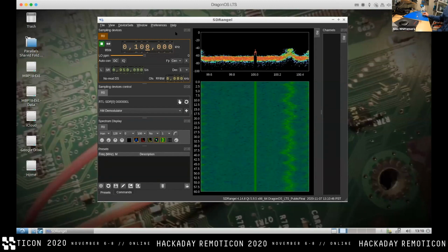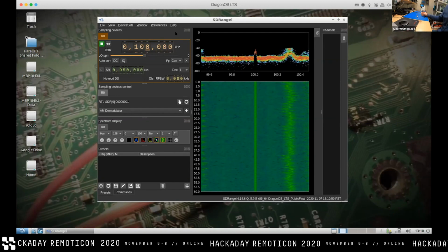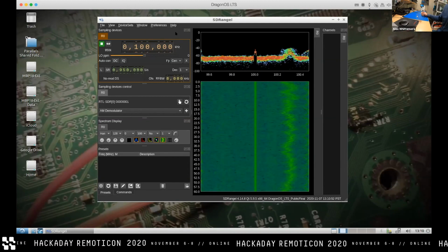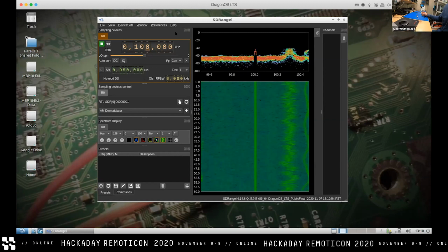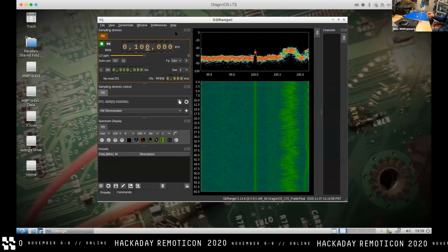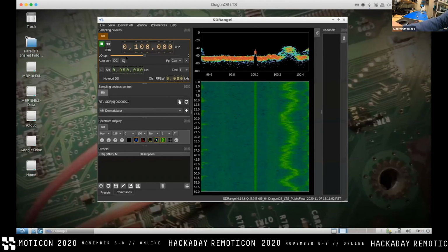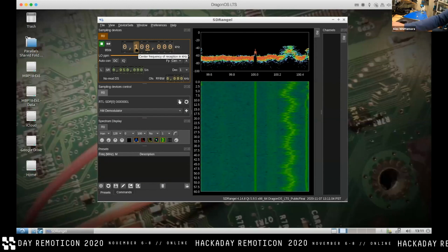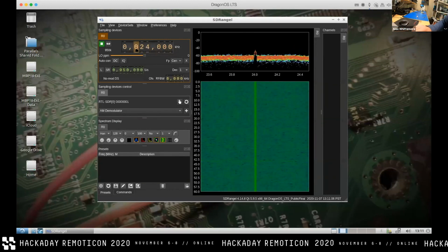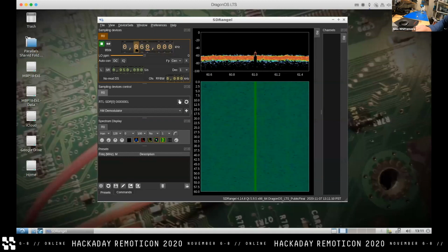like flash the firmware and then browse around, basically you can look for the oscillator at 24 megahertz or the signal in question at 50 megahertz, but we'll get there in a sec. I'll show you that board in a sec. Before we go there, I'm just going to quickly retune this SDR to 60 megahertz.